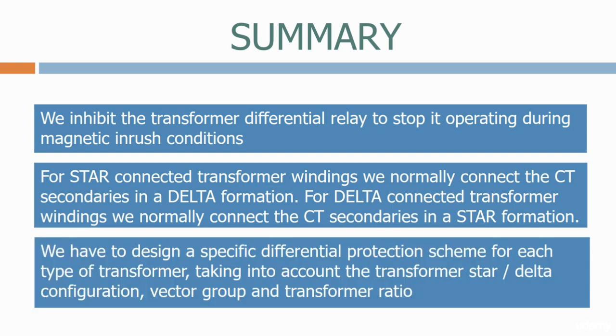We have to design a specific differential protection scheme for each type of transformer, taking into account the transformer star-delta configuration, the vector group, and the transformer ratio.